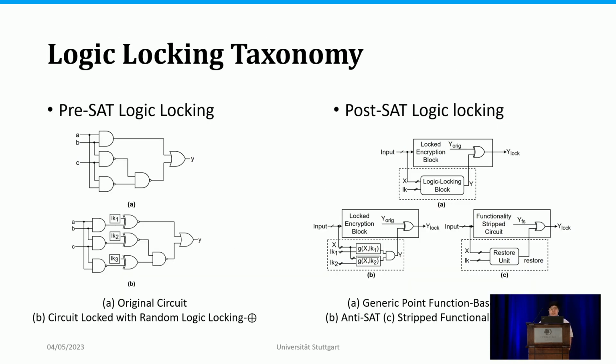For this purpose, we considered two broad families of logic locking schemes, pre-SAT and post-SAT logic locking. For people who are not familiar with them, on the left-hand side you see a simple example of random logic locking using XOR and XNOR insertions, such that the circuits shown in figures A and B would be functionally equivalent if and only if the correct logic locking key, LK, is applied to the circuit. We consider two variants of this scheme, using random AND and OR insertions and using random XOR and XNOR insertions.